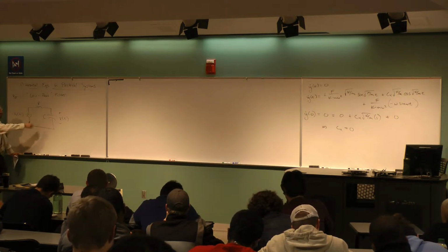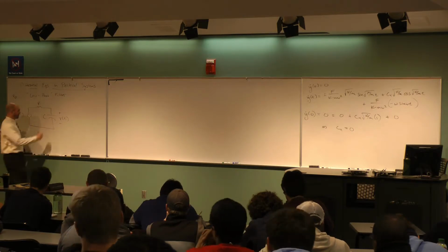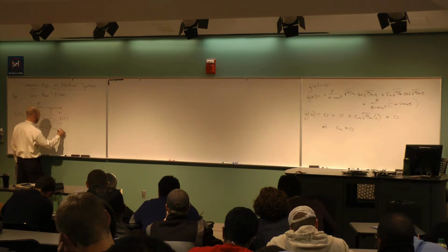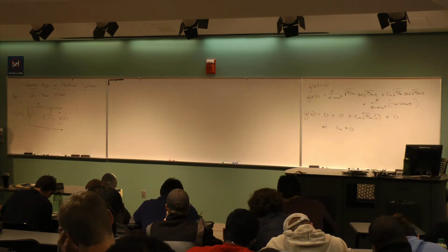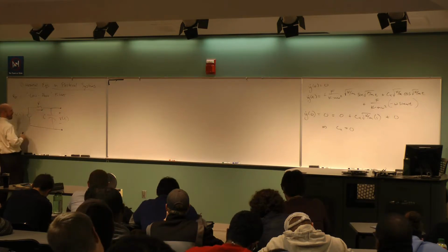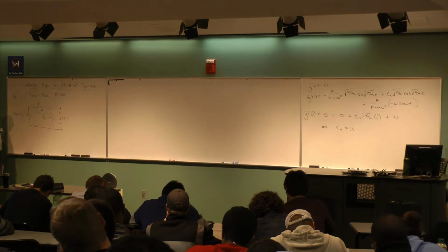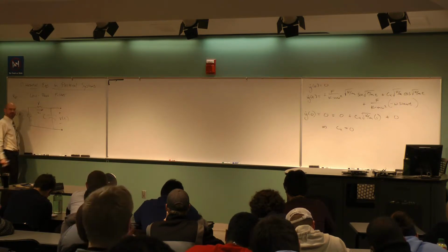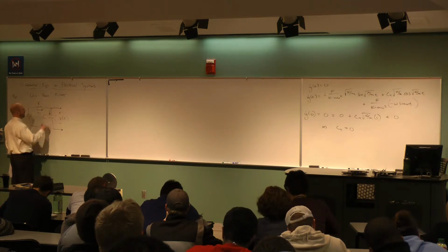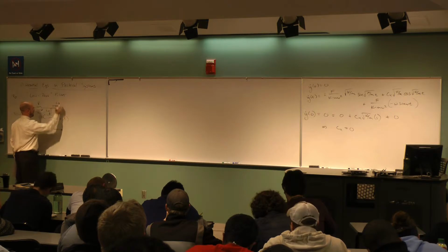There are a number of different ways you can do the analysis. You can think about it in terms of Kirchhoff's voltage law. Let me look at it a different way, the way we have it here in the notes. If you think about measuring this output voltage across two open terminals, one way to do the circuit analysis is to say that essentially I've got three currents here. I've got I1, the current going through the resistor, and then I reach this intersection. The current can take a corner this way, and that would be I2, or the current can go straight, and that would be I3.